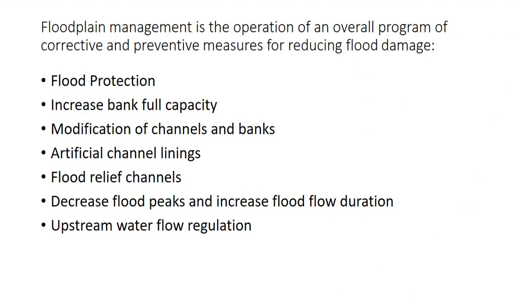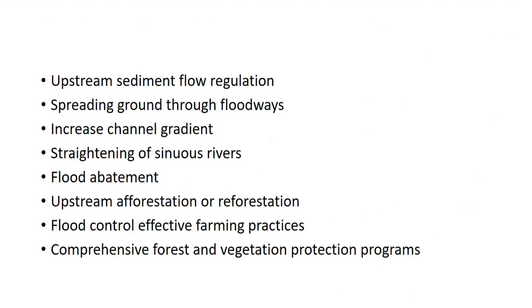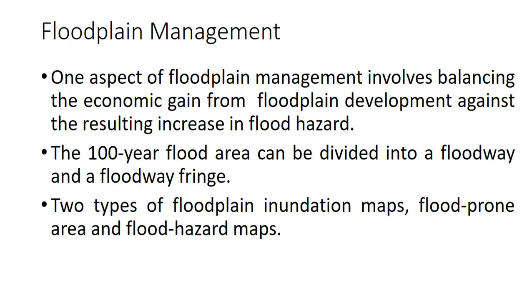So some of the following are your management controls for your floodplain. One more aspect of floodplain management involves balancing the economic gain from floodplain development against the resulting increase in flood hazard. So the 100-year flood area can be divided into a floodway and a floodway fringe. On the next image we will show. And finally, floodplain and drainage maps are your flood-prone area and flood hazard maps.